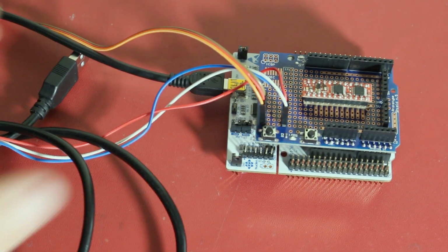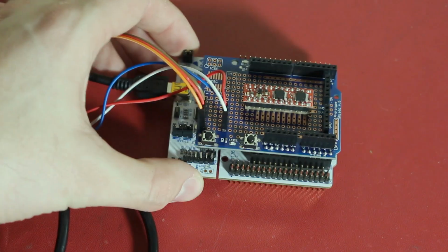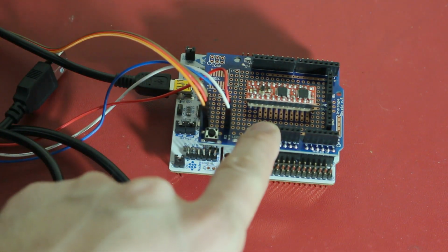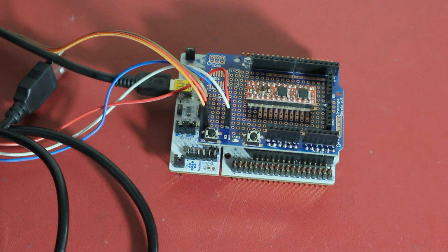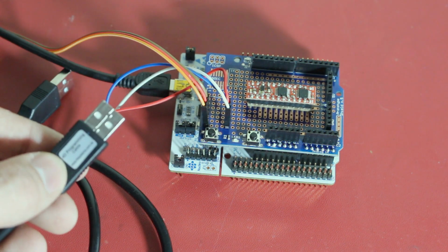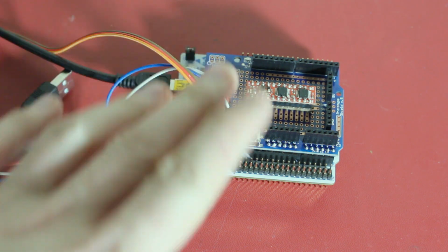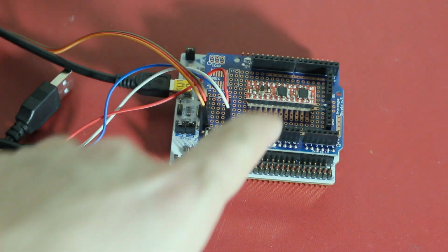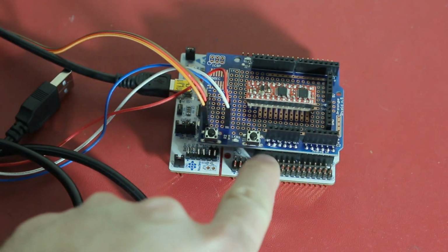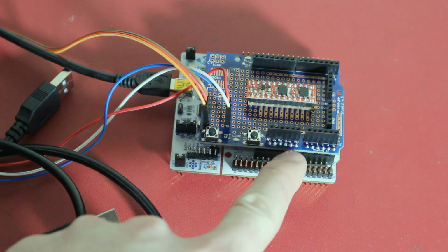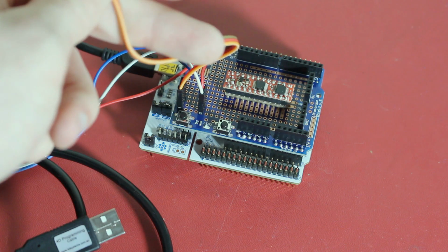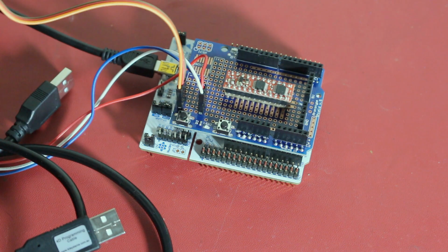So for this project, I've got the STM32 board set up here, and I've got an Arduino shield on top of it. The Arduino shield allows me to connect my UART adapter here for serial communication to command the PWM on and off, and then I've got a logic level translator here to shift up from the 3.3 volt of the STM32 up to the 5 volt output that I need for the circuit that I'm driving.